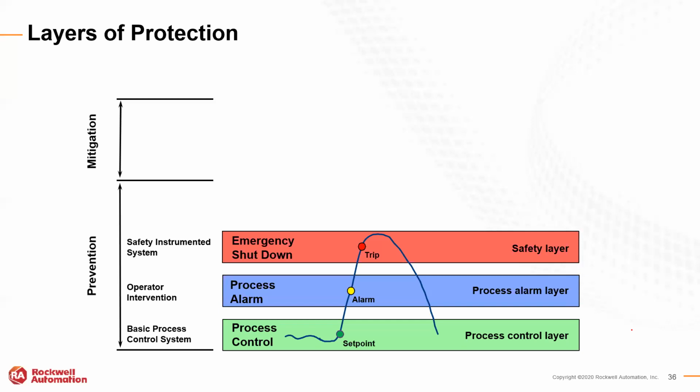Let's say you picked the same kind of valve for everything in the system, and then you went and used a different chemical that had a caustic effect on that valve body, and it froze the valves. Well, if your safety system had the exact same valve as the process system, and it froze as well, now you've just, with one action, taken out two different layers of protection at one time. So that's why it really needs to be independent and diverse.